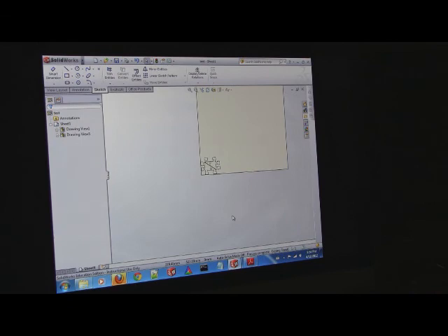Now we can select and change stuff on the laser cutter, but don't worry about it. This is a black box for you. The reason we do this is that in plywood and 3/4 MDF, if you make your holes D minus 0.4 millimeters, it will be perfect, spot on, press fit worthy or slip fit worthy, whichever you want. That's the reason we're doing that.